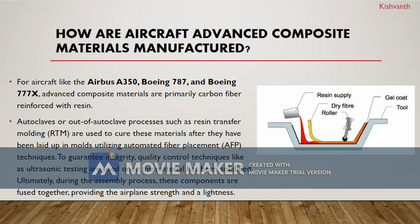So now how are aircraft advanced composite materials manufactured? For aircraft like the Airbus A350, Boeing 787 and Boeing 777X, advanced composite materials are primarily carbon fiber reinforced with resin. Autoclaves or out-of-autoclave processes such as resin transfer molding are used to cure these materials after they have been laid out in molds utilizing automated fiber placement techniques. To guarantee integrity, quality control techniques like ultrasonic testing are used once the material has been solidified. Ultimately, during the assembly process, these components are fused together, providing the airplane strength and lightness.